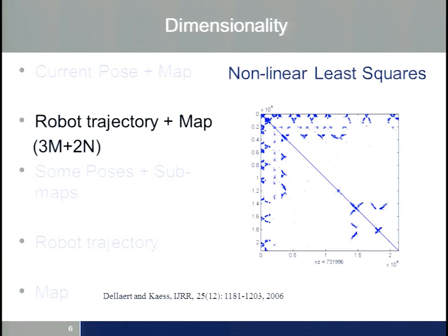But it turns out that Frank Dellaert and his group showed that the Jacobians and the Hessian in the associated optimization problem are very, very sparse. And you can indeed compute this very quickly, and you can solve this problem quite effectively. So although on the basic simple look at it, intuitively it doesn't look good, it actually turned out to be a very good solution. That was a big surprise at the time.